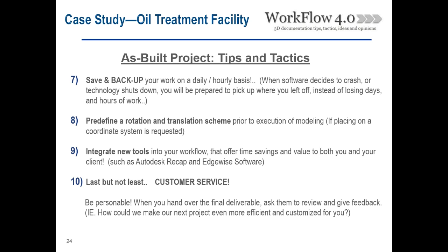So you can use targets with ReCap. I was under the impression that it was purely targetless. It is purely targetless. It doesn't have a way, like other software does, to automatically find targets, but you can place individual points to help if you're having registration issues. It does have some minor other tools, but not in a way that other software automatically finds all those targets and uses them. So it's not meant for using targets, no. Got it. Understand. All right, great.